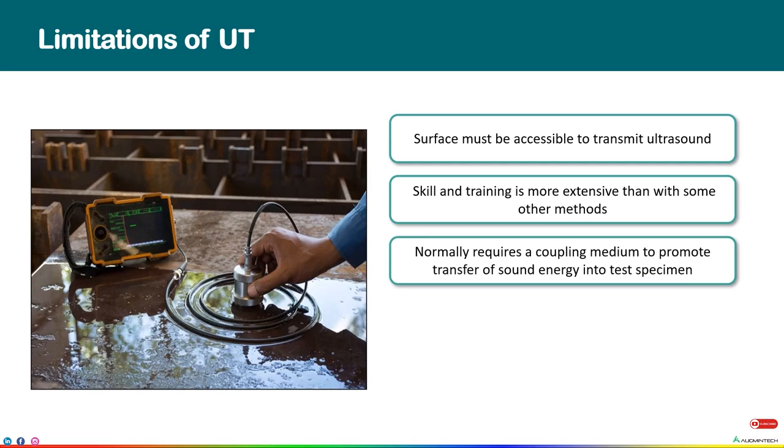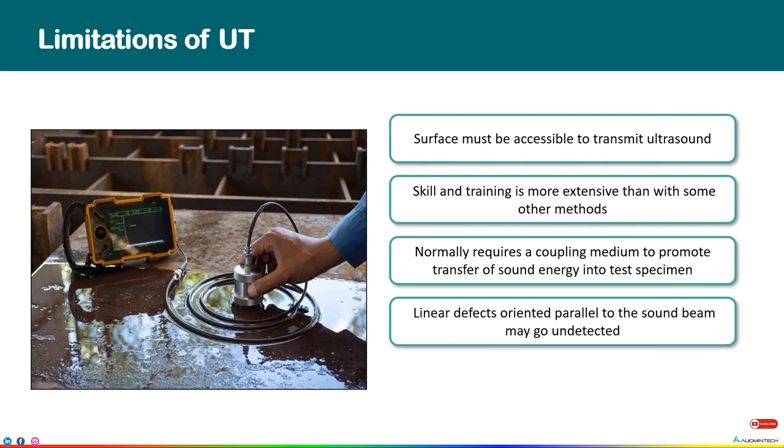It normally requires a coupling medium to promote transfer of sound energy into the test specimen. A UT technique cannot work without a good couplant. Therefore, this technique can only be used on those objects on which a couplant can be applied.